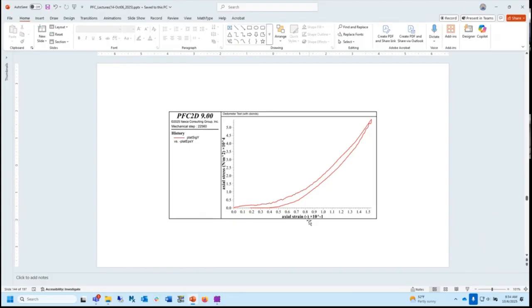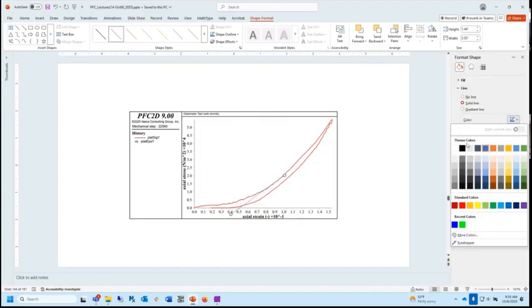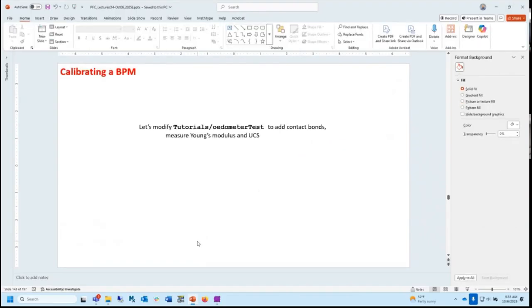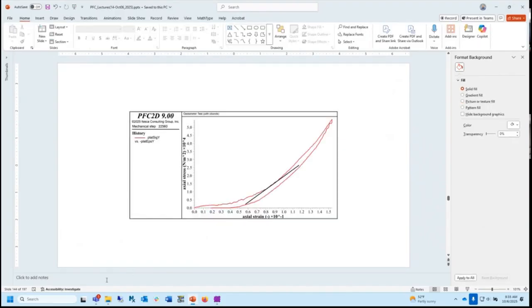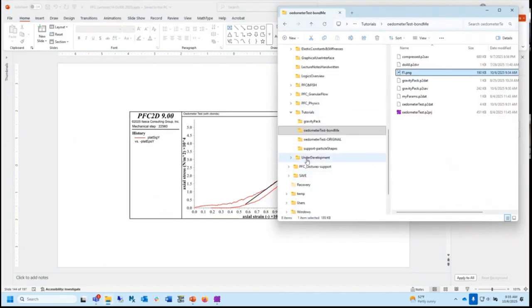Axial stress, axial strain. And based on what we were saying, this slope is what we're going to call what? What's the slope of the stress strain curve? Constrained modulus. Nice job. It's the constrained modulus. It's not the Young's modulus. This does not have the boundary conditions of a Young's modulus test, of a UCS test. Let's take a quick peek at what I mean by that. This is actually pretty cool. I didn't know any of this stuff when I started doing this work.